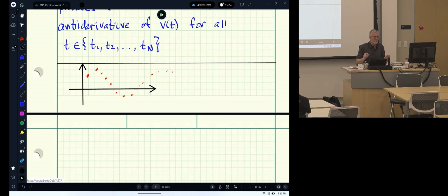Interpolate, and then differentiate the interpolated function. So use regression like you were taught in Rob 101, and use any class of functions you want, RBF, monomials, sines and cosines, and then you differentiate those. It's actually a very powerful way to compute derivatives from encoder data, which is discrete in time.